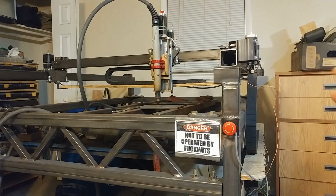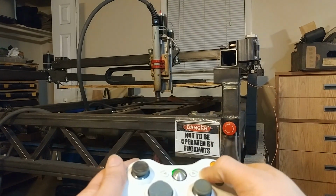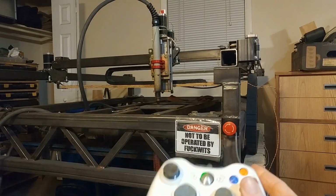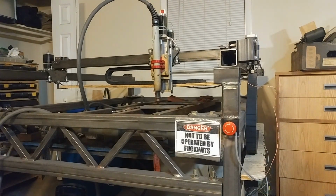We're not getting any plasma right now because the Hypertherm box itself is turned off, just for the sake of shooting a video. But LinuxCNC thinks the torch is running. So now the manual control here does also work, as you can see from the flag up top of the motor spinning around. And that will remain active anytime M3 is active during the G-code program.